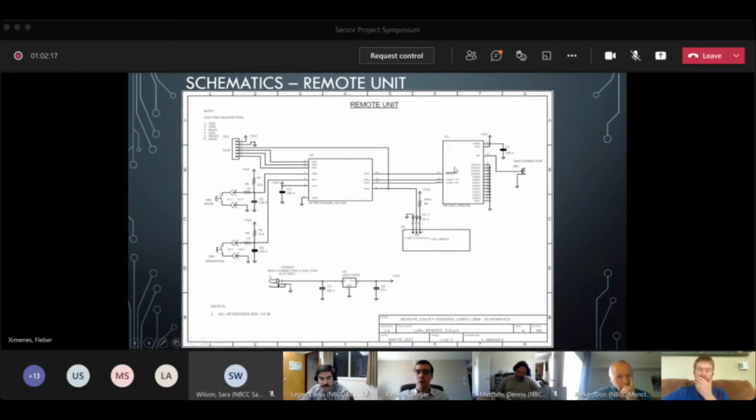Well, this LoRa module has a channel separation. You can enable that feature on the LoRa module. So you put each sensor or remote terminal unit, RTU, on one channel, and it doesn't get information from or interfere with another channel. I didn't use it because I only have one. I understand. Yeah, but it is available on this chip specifically. Channels, very useful technology.